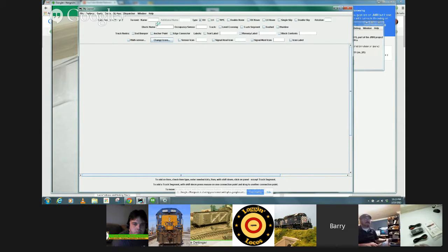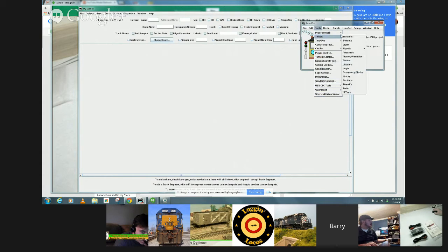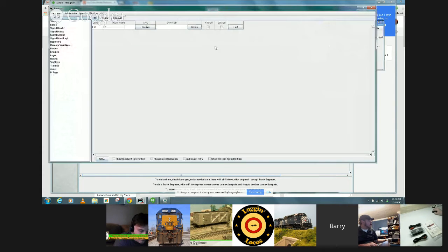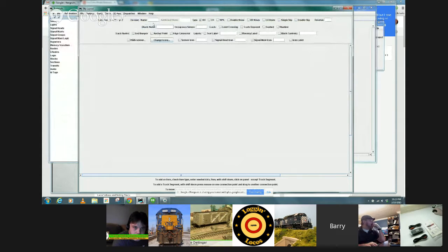So let's start with, we will put ourselves down, turnout. So we had, that's the thing, I always got to remember to keep my table open. Turnout S1 for spur 1. So now we'll go back to here, and we'll put S1 for the turnout name. It'll be left-hand turnout. Now you just hold the shift key down, click on the screen, and there's your turnout.